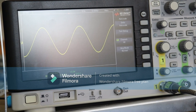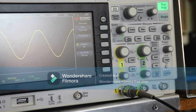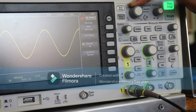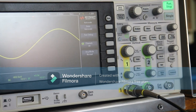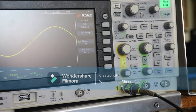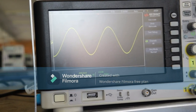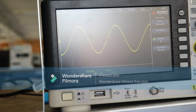Now, there are quite a lot of buttons, or rather knobs, which you can adjust, which might be confusing at first, but the main 3 you should remember are the horizontal scale per division knob, which either expands or contracts your wave horizontally, your vertical volts per division knob, which expands it vertically, and then, like I mentioned, 3, your auto scale, which typically would do the job for you, so you don't need to play around with your horizontal or your vertical scale. Okay.